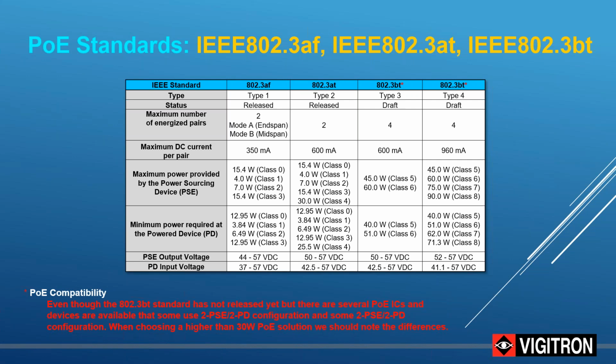And as we spoke about it, we also indicated that this amount of voltage is not always consistent for every single manufacturer, and that it could range more towards the higher end than the lower end. And as you can see, when we shift over to 802.3at and the different standards for PoE that come after that, the lower end is actually raised to 42.5 volts DC. So regardless of what we're putting in as an extender or repeater or any other device that increases the distance, our system really doesn't care. It expects to see this in order to work. So the ability of maintaining this becomes a critical component.